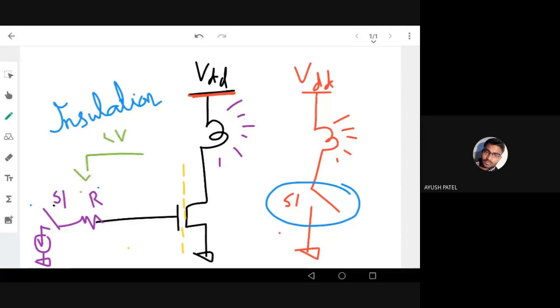Low voltage circuit. Why? Because I need a very small voltage to turn on a MOSFET, maybe 2 volt, 3 volt. Even a power MOSFET needs a very small voltage to trigger it or make it on. Right? So that is the gate part. Here is the low voltage part, very low voltage, 4 volt or something like this.